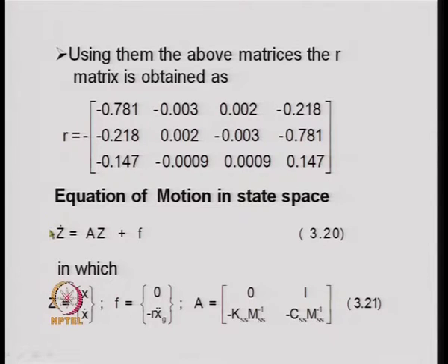In one case we are writing the equation of motion in terms of the relative displacement, and in the other case in terms of the total displacement, and on the right hand side we had a KSG matrix, and we require ground displacements instead of ground acceleration. Those two multi degree of freedom second order differential equations can be written in the state space form as before.